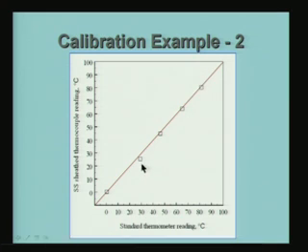If it is a flow measuring device, for example, I would not go to the extremes, I will only do it in between the range. So, this range will be known to us, and therefore, we will pick up the values like this. In this case, you can see that there is a difference between the thermocouples. This is a shielded thermocouple, stainless steel shielded thermocouple, K type I think, and this is the standard thermocouple.